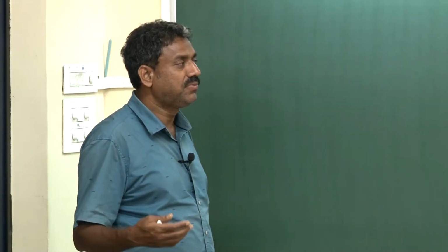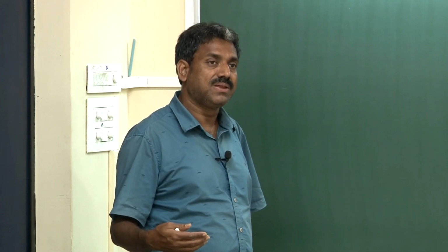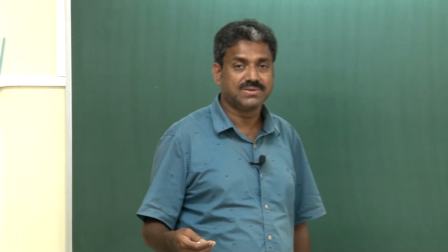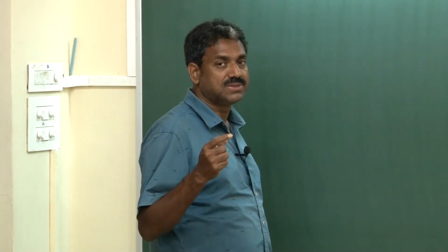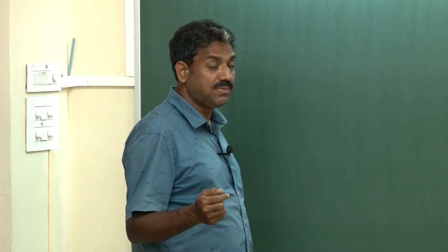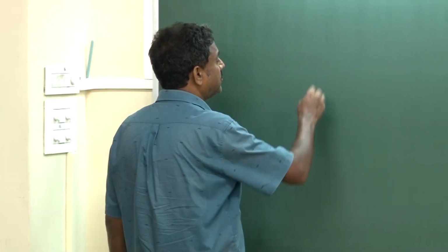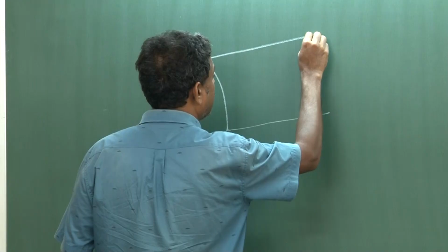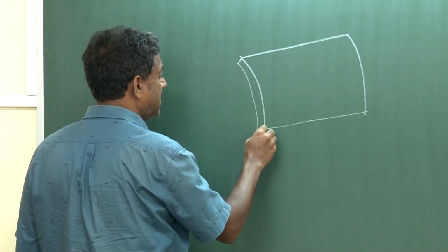So, we have two field variables, one is W, that is the out of plane deflection, and the other field variable is essentially the stress function. What we know is that in plane forces can be derived from the stress function, and the governing equations for the equilibrium as well as the compatibility equations we derived and have written down, and now we are trying to solve them. Of course, because of the complicated nonlinear form of the equations, we are going to consider a simple panel, which is a cylindrical panel.